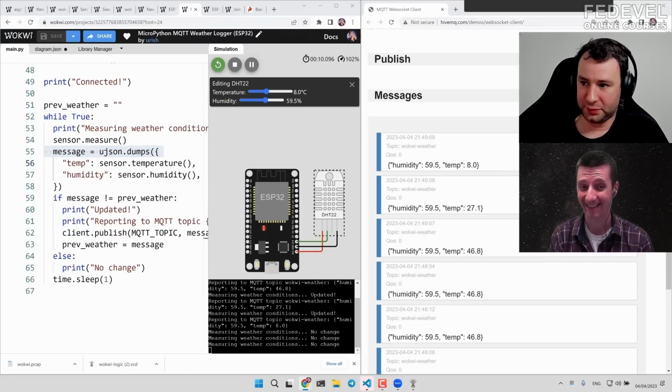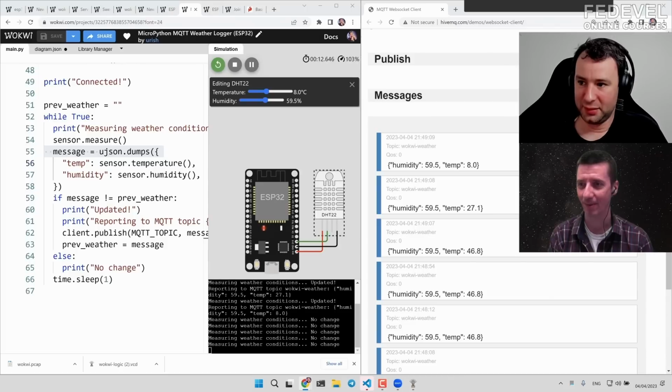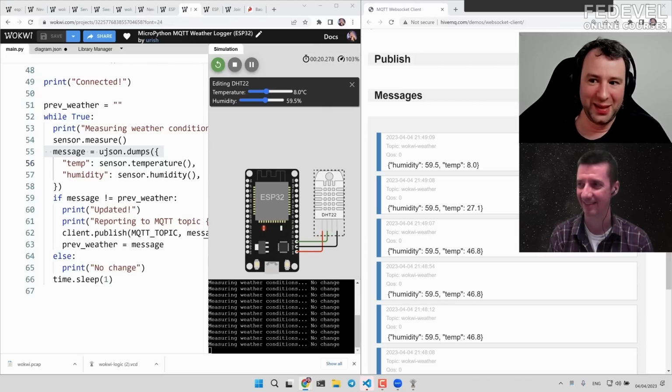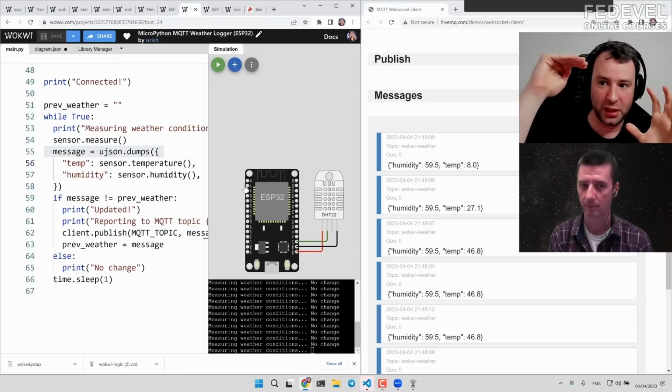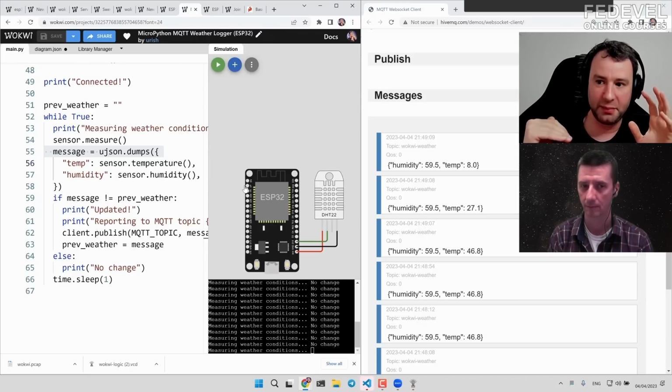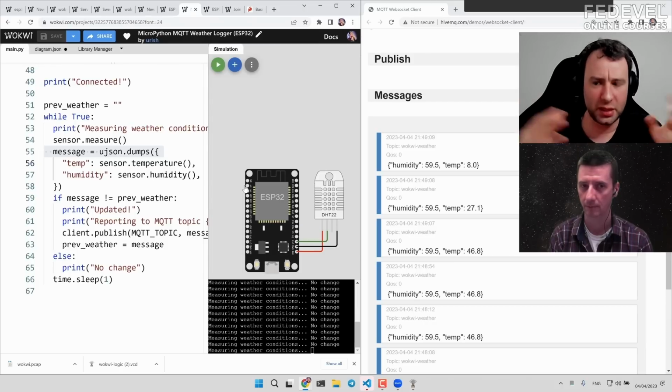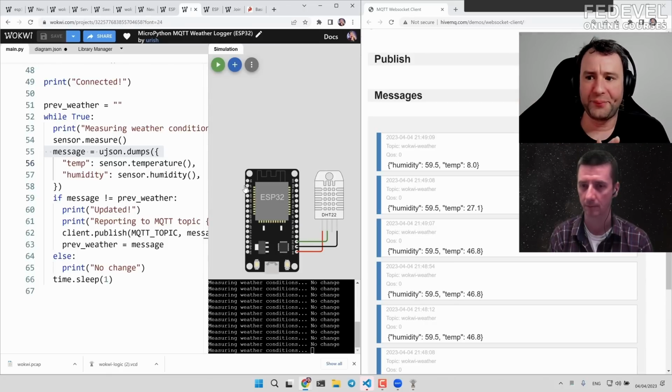And wow, really, I'm very surprised you simulate all these things. Thanks. So yeah, the simulator itself doesn't really think about what it's simulating. It's just trying to simulate the ESP32 microcontroller and execute the binary files, the firmware files, one instruction at a time, and all the peripherals like UART, SPI, and etc. But it takes a lot of work to make it so that you click play and